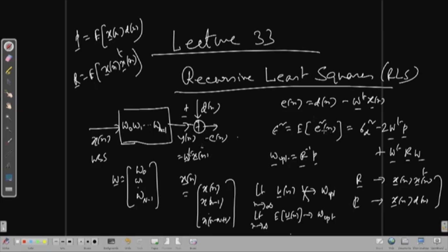But you see, there is no E operator, expectation operator. But the value of that will be almost equal to epsilon square if you have many samples. Therefore, if you plot this epsilon square against the filter weights, it will be a quadratic surface. If you take the sample average, that is e square n averaged sample-wise, and plot that also versus W, you will get more or less the same identical curve, because for any W, the sample average will be following this epsilon square very closely.